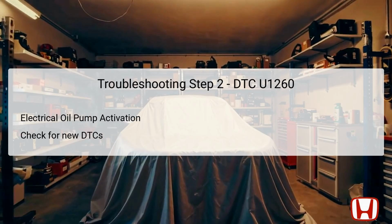In the second troubleshooting step, it's essential to verify the operational status of the auxiliary transmission fluid pump. Select the electrical oil pump activation in the function test menu on the HDS. By activating the pump for at least 5 seconds, you can observe its immediate performance. Following the activation, again, check for pending or confirmed DTCs using the HDS. If the U1260 DTC appears, you have confirmed the failure.